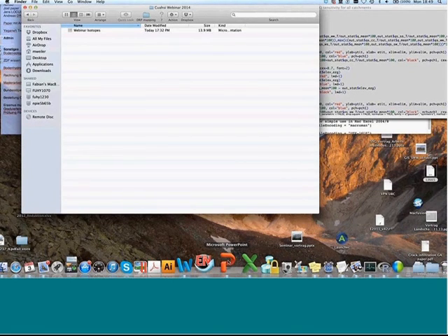If we use, for example, on the one side the soil moisture information and try to predict the dynamics in the soil moisture based on the HYDRUS model, we get certain soil properties, and we then make a forward prediction of transport, and this may be completely different from if we use the soil isotope profiles directly in combination with the soil moisture.